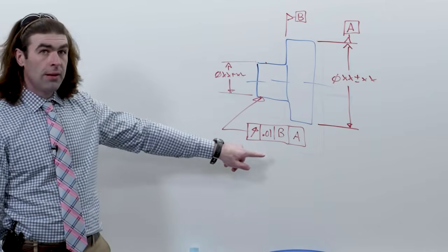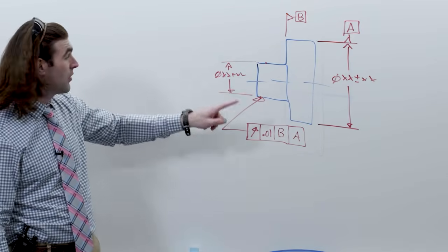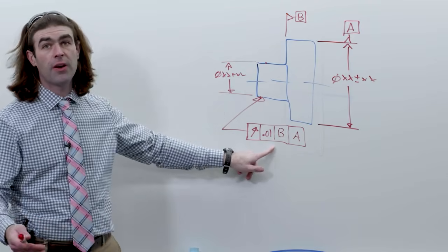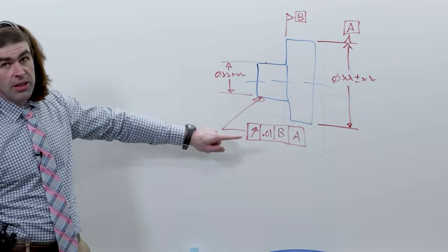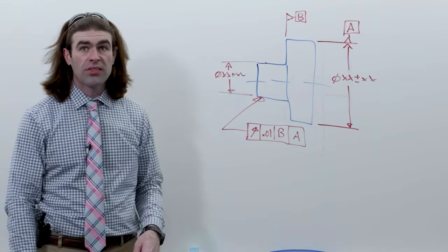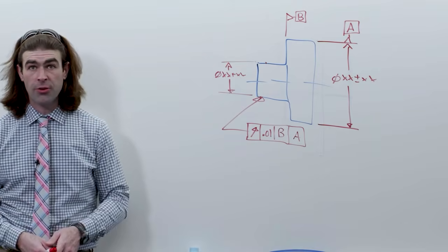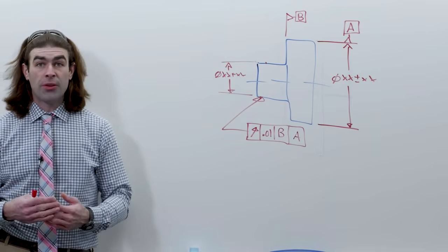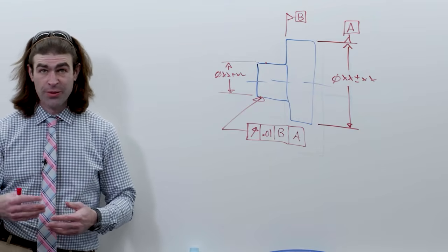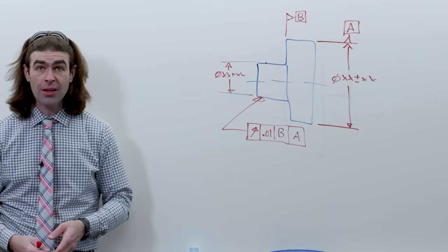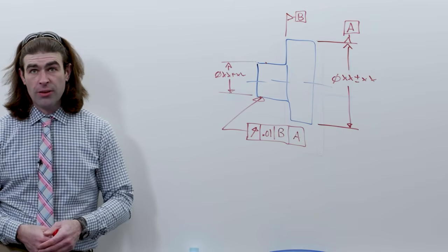The outer boundary for a runout tolerance is the largest size, the MMC, plus the geometric tolerance for an external feature. The inner boundary is, in this case, the LMC minus the geometric tolerance. So if you're doing a tolerance stack up, it's pretty straightforward to figure out what your boundaries are. There's no bonus tolerance with runout tolerances, so I wouldn't apply it to anything with like a clearance application. But anything that spins, especially at high speed, runout is a good tolerance to apply.